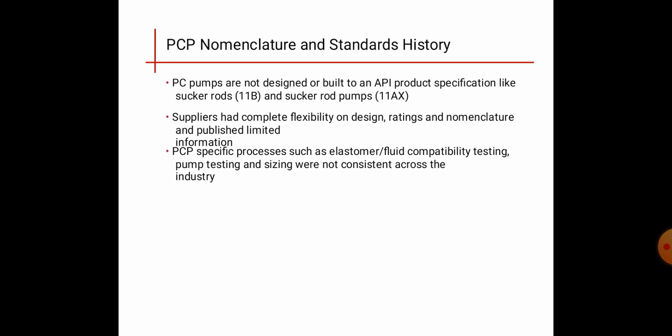Generally, the PCP pumps are not designed as per API product specification like sucker rods and sucker rod pumps, because the design, rating and nomenclature of the PCP pumps depends upon the market, and the supplier has flexibility as per the requirements.